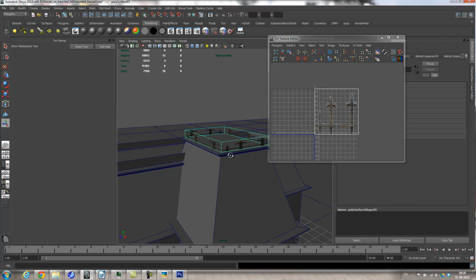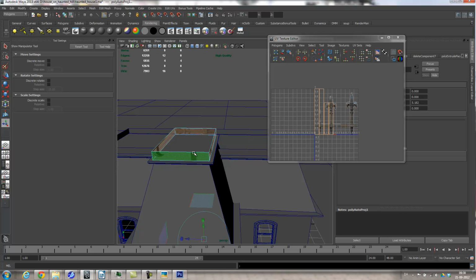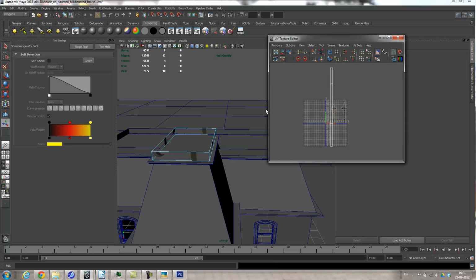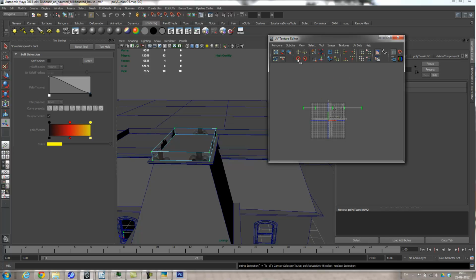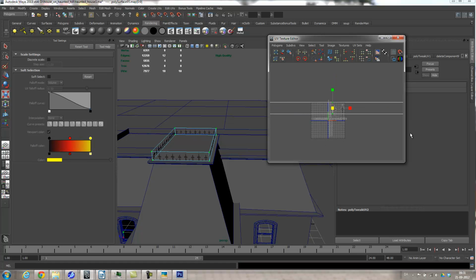Then what I'll do is I will grab these edges here. I'll actually do it differently. I'll grab these and then I go automatic mapping. There we go. Automatic. Yeah, and then I'll grab the edges here for these, and I'll do the move and sew. So I'll make one long strip here, like so. Okay, grab all these and rotate them twice, then move it over. Actually, just scale it up until it fits.